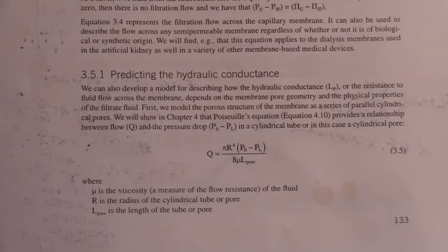But even going in the lab and doing a simple experiment like that, it takes time, it takes money, and sometimes you just want to be able to predict what the flow rate's going to be, and that means you need to know what the hydraulic conductance of your membrane is. And we can predict that by creating a mathematical model of the membrane itself. And then we can use that prediction to do design calculations and try to optimize the design and say, okay, this is the way we ought to go, and then build a prototype and test it and see if it actually works.